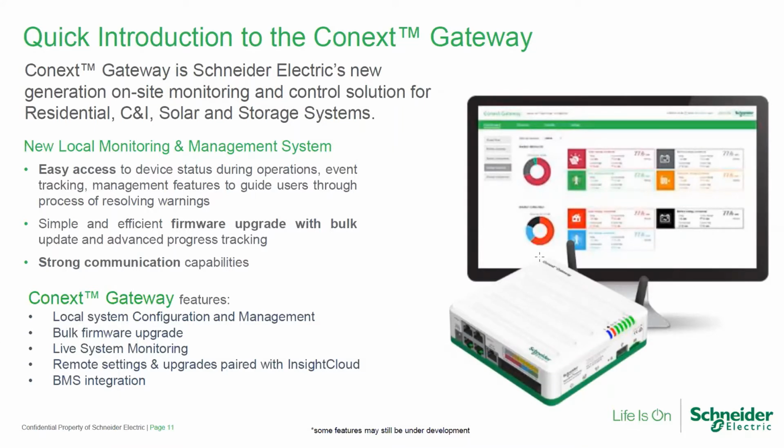In addition, it has an auxiliary port, which you can see on the bottom right of the device, which allows you RS-485 communication and CAN communication. So it comes with 2 CAN ports and 2 RS-485 ports, which allows a very large amount of devices monitored at the same time. So the gateway, as per its name, has the function of pulling the data from all these devices and delivering that to the cloud server on the Schneider offices, which actually powers up the ConnectInsight website, which we will see a little bit later.